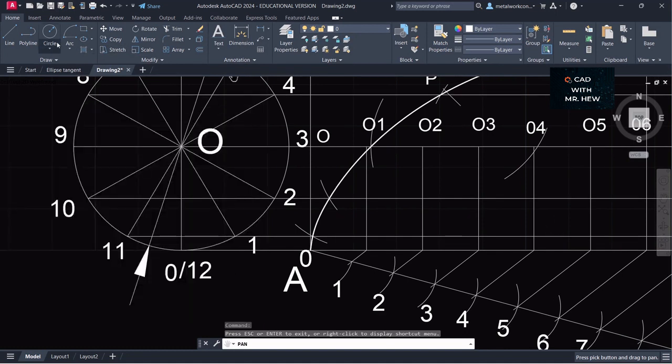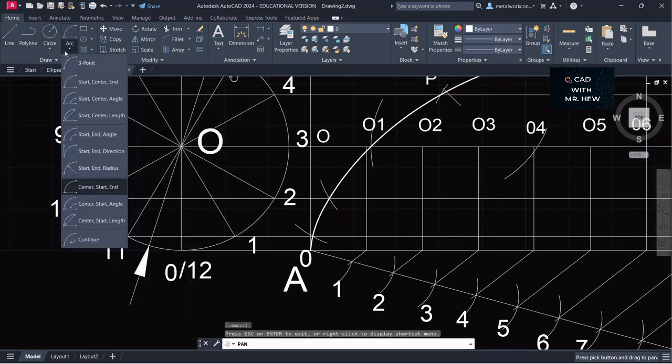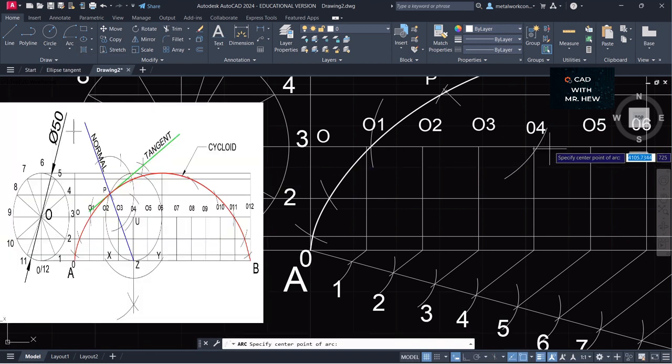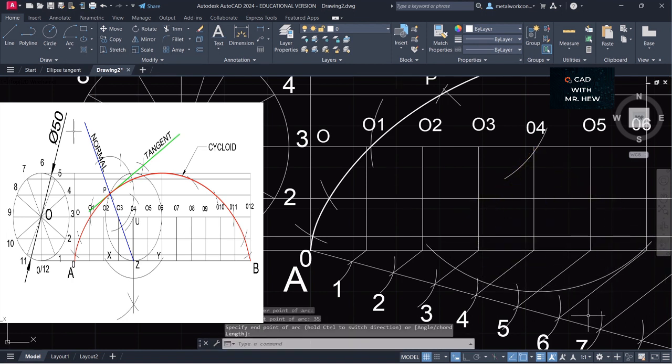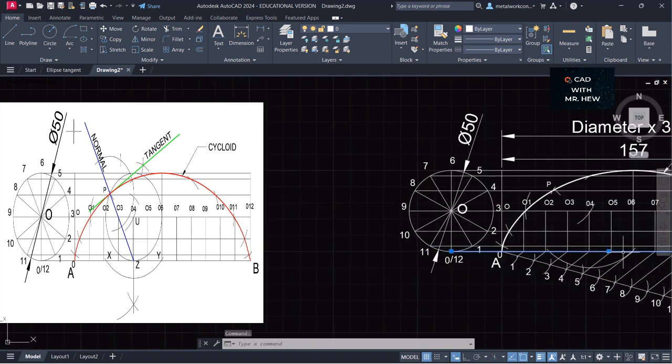All right. So this is how you drop a perpendicular. You're going to go arc, start, center, and the center will be at this intersection. The radius would have to be greater than 25, so we'd have to choose something like 35, enter, and see there. Where this arc intersects the baseline, which is this line, we're going to mark another arc from there, right?